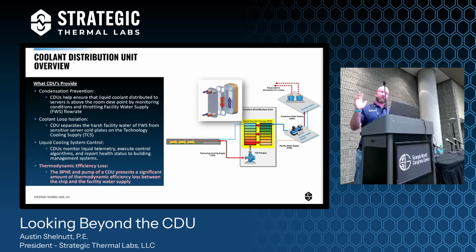CDUs have many positive benefits. Condensation prevention, coolant loop isolation for harsh water chemistries that might be present in the facility water supply. They give you a control and monitoring point for your liquid cooling system health. All those things are great, and a host of other benefits. So don't get me wrong, CDUs are valuable in the data center space, and not everybody is ready for a non-CDU world.